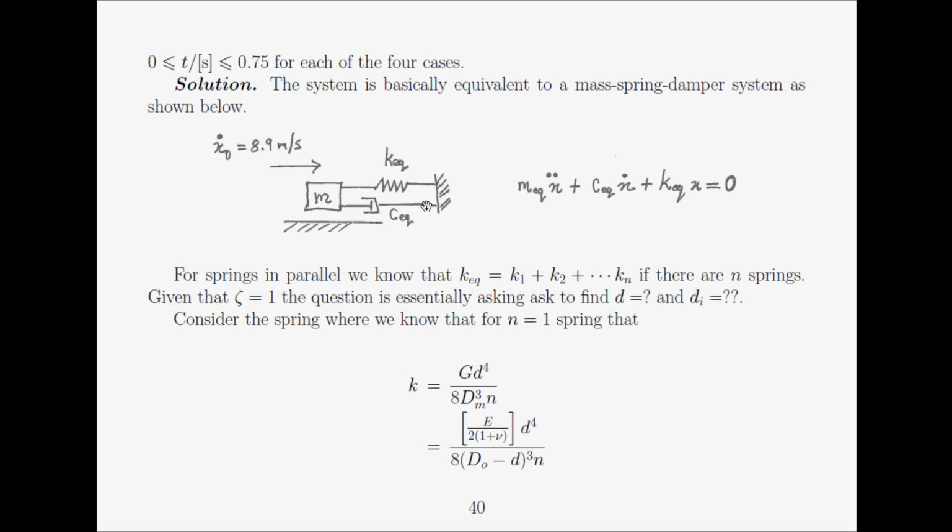And the entire system of the train and shock absorber system is effectively a mass spring damper system, and it has the standard equation that we see over here. We've analyzed this equation before. We've also commented that this equation with m, c, and k is effectively equivalent to a system with an omega n, a natural angular frequency, and a zeta, a damping factor.